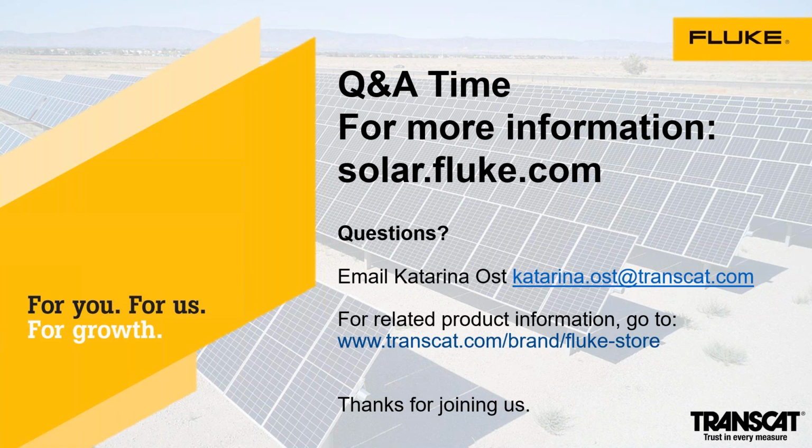So if you're working in a 1500 volt environment, you're going to want to make sure that you've got the 1500 volt test leads. Another thing to point out that I didn't mention: everybody who has worked with a multimeter before knows the test lead probes come with a little plastic cap that you can remove. But a lot of people don't realize that when you remove that plastic cap, it changes the category and voltage rating of the test leads. And it also makes it much easier to arc between test lead terminals. So please make sure that you don't take those off unless you really have to, and don't lose them.